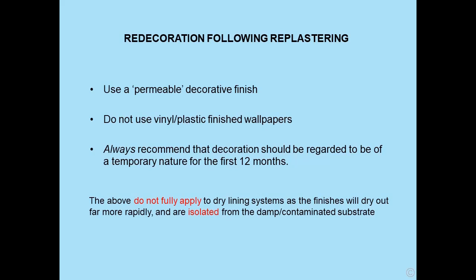Frequently people will apply an expensive decorative finish, paint or what have you, and within a couple of weeks it starts to be a problem because nothing has fully dried out. Do bear in mind, of course, that the above does not fully apply to dry lining systems because, in essence, they're isolated from the damp contaminated substrate.